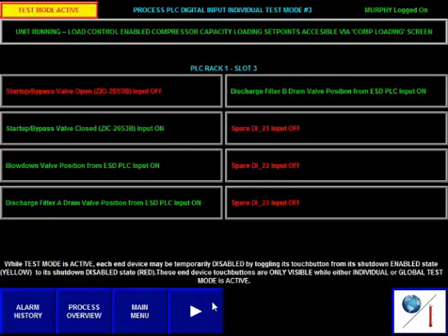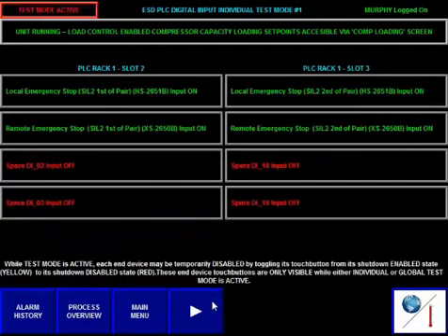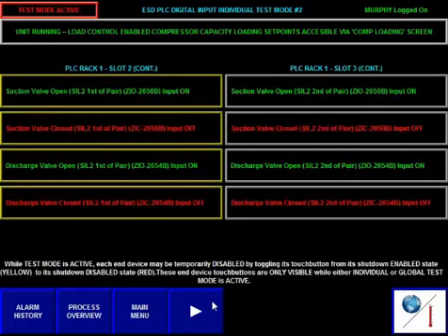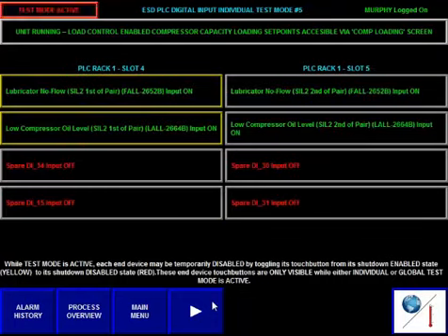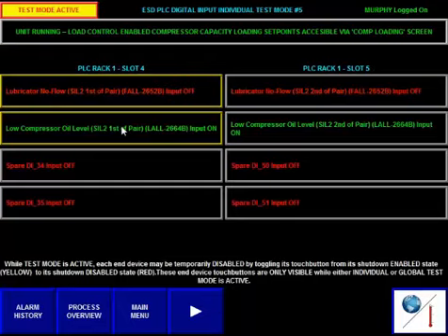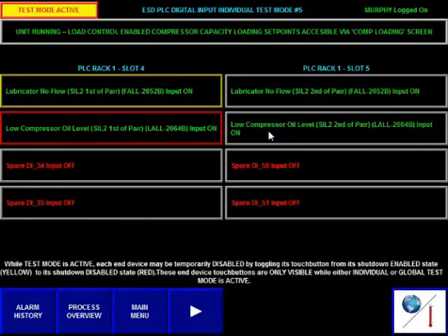oil level switch. I'll touch the switch. You see the timestamp indicated we went into test mode. It's highlighted in a red bar. That means that the input is in test mode and it's bypassed from tripping the machine. Now I'll remove a fuse to create a trip.